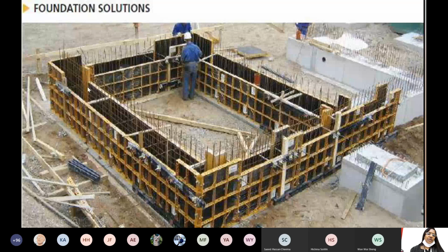This may be a plinth level, sorry, in your terms, it's a basement. This is the ground, right? This is the beam, we call this a belt beam. It's acting as a belt beam between the foundation and the superstructure, okay? We call this a basement or a belt, right? It is constructed to transfer the load from the superstructure of the walls to the foundation. See here, after the foundation, it is a little bit smaller than this one.